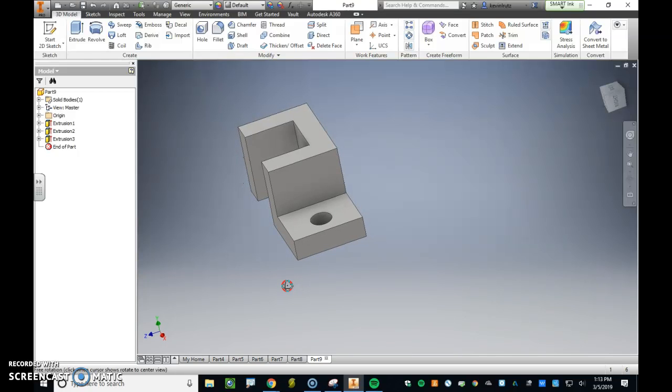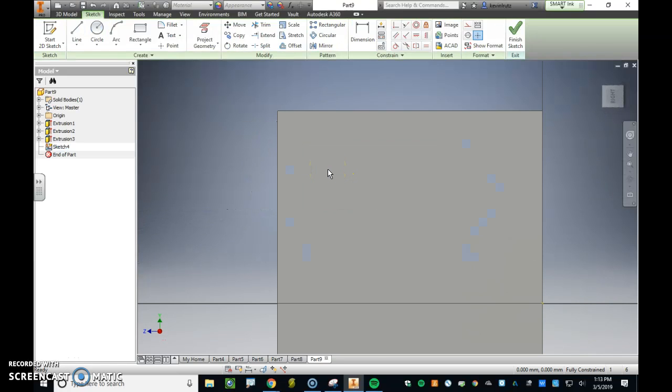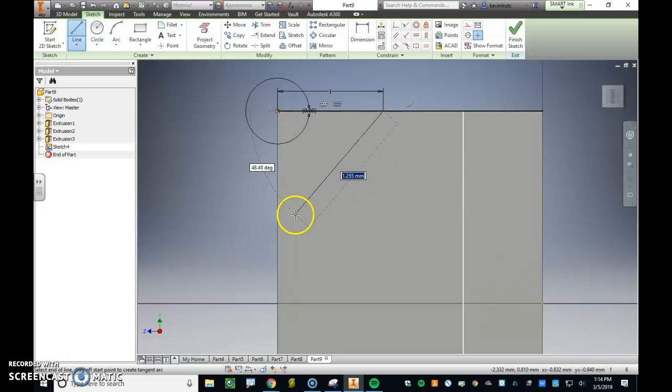Look, gorgeous. Now what I'm going to do is my last bit. I'm going to draw on this edge. Now if you look at the dimensions on page 36, take your line tool from that top corner. I make sure I have 90 degrees. I can also just type, I press tab, 0 degrees, and I'm going to make this 1, should be inch, whatever. Now, same deal here.